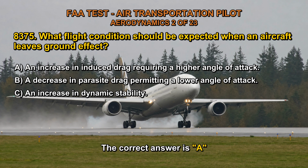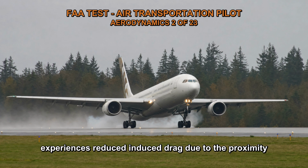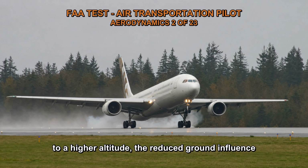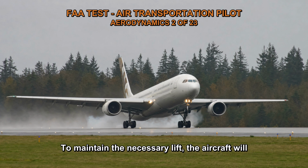The correct answer is A. When an aircraft is in ground effect, it experiences reduced induced drag due to the proximity of the ground, resulting in better lift-to-drag ratio. As the aircraft leaves ground effect and moves to a higher altitude, the reduced ground influence leads to an increase in induced drag. To maintain the necessary lift, the aircraft will need to increase its angle of attack.